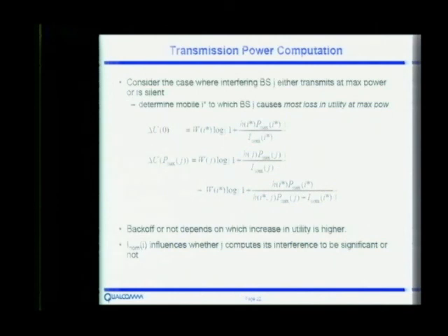If you're in a topology where you don't have a dominant interferer and you have a bunch of interferers causing a lot of interference, you want less backoff on average. So this just helps you bias towards more backoff or less backoff. It's not exact. I don't have any theoretical statement that says this is optimal. But this is one knob, like a soft backoff, which allows you to control that.